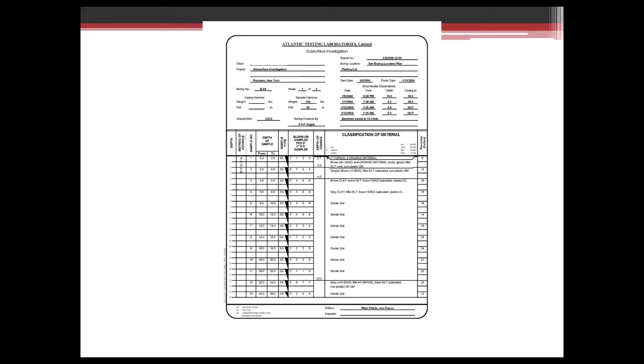Those groundwater observations are date and time specific, and that can be important, especially the date, depending on the time of year. If you notice, these water readings were all taken in January, and I can tell you that January in particular, because I remember this project very clearly, was very cold. So those water depths at 6 inches below the surface, that was actually frozen water that we had to break the ice, and then it was solid ice below that. This was in a low area.